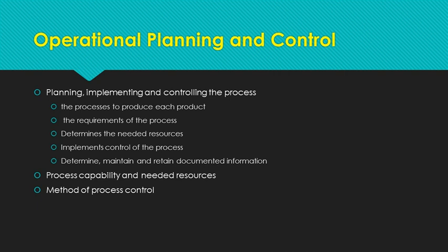Another example is a pharmaceutical company, and they will control the parameters of the batching process and test the effectiveness of those controls prior to sending the material to filling. Filled material will again be tested to ensure no contamination occurred in the filling process before sending it to packaging. Packaged material will be warehoused and the location of each batch of material going to each customer will be identified. The product has a very specific expiration date, and records will be kept for the effectiveness period plus an additional period determined by the organization.